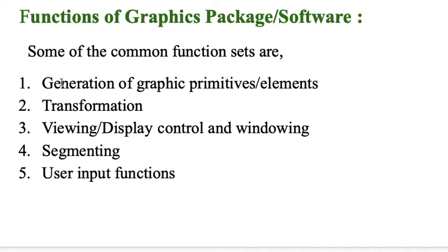The graphics software must perform a variety of functions to fulfill CAD CAM requirements. Some common functions are the generation of graphics primitive elements. Graphic primitives are two-dimensional and three-dimensional geometrical elements. The two-dimensional graphic primitives are line segments, arc, circle, parabola, hyperbola, and ellipse. The three-dimensional elements are box, cylinder, prism, sphere, cone, and torus.